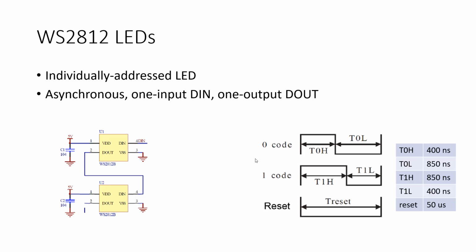Yes. But that's all done inside the LED, so you don't have to worry about that. In other words, we're not having to send these LEDs pulse width modulated signals, because that's handled inside the LED itself. Apparently they have a pulse width modulation circuit inside them, right? All you have to send them is a 24-bit RGB value, red, green, and blue, 8 bits each, and then the LED will just turn that color, right?